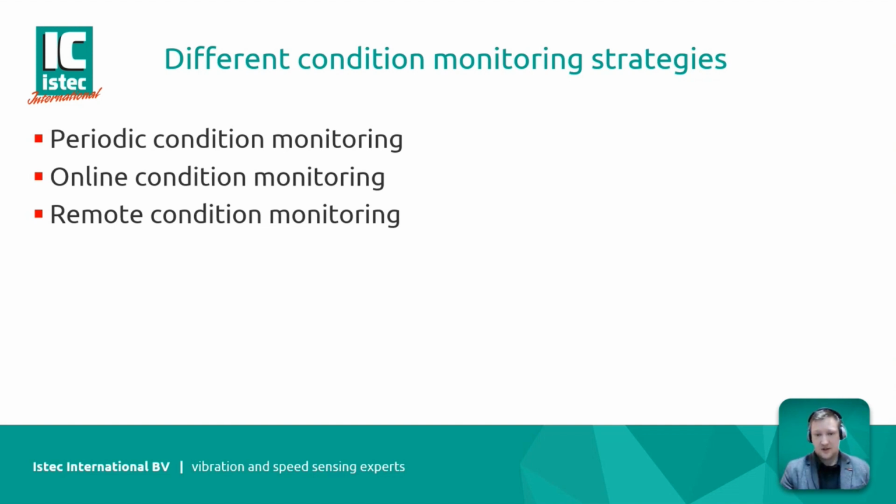It will continuously collect the data, and this data will be continuously processed, and all the key parameters which you want to monitor can be presented in real time. But you can also look back 1 day, 3 days, 5 days, 1 month, whatever you want. And you can use that to determine if the machine starts to degrade or not. And that can be used to initiate maintenance or to involve specialists to do an in-depth analysis.